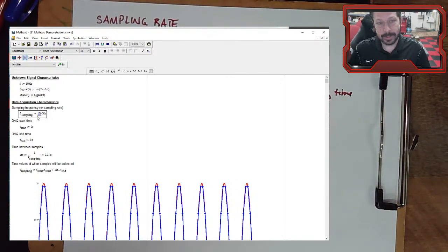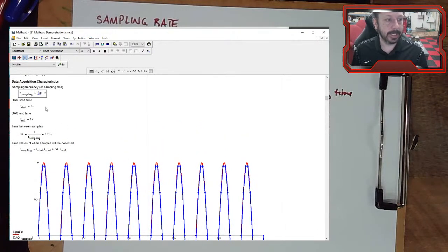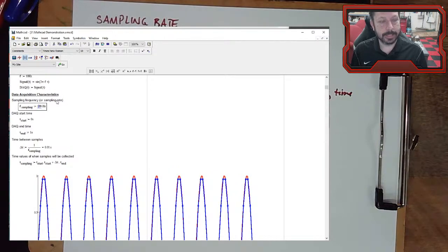So even though you can't capture the 60 hertz because your machine is too slow or whatever, those higher frequency signals might alias down just the way this one did when it went from 10 to 1 or 2 or whatever, or 0 even, and show up in your signal. So you build a filter to get rid of anything higher than what you're looking for.